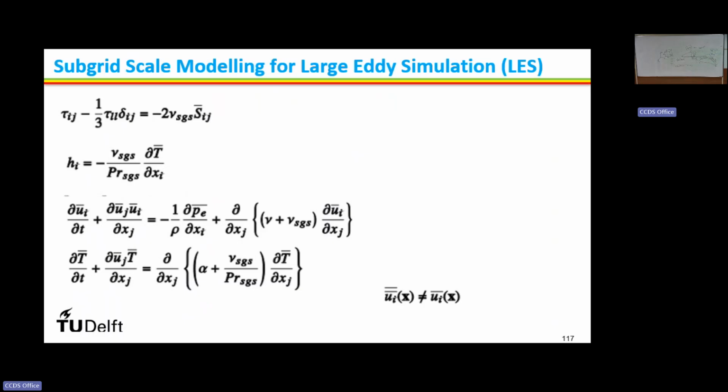Someone was asking me in the morning session, what is turbulent Prandtl number? Similarly, if you are doing RANS computation, we will get a number that is nu_T by Pr_T. This Pr_T is called the turbulent Prandtl number. It is not a property of the fluid, rather it is a property of the turbulence. Normally a value between 0.8 and 0.95 is used. It's a constant value; sometimes they use around 0.95.